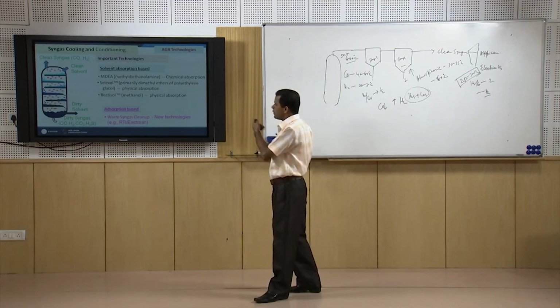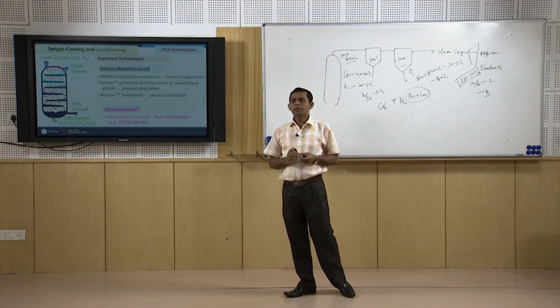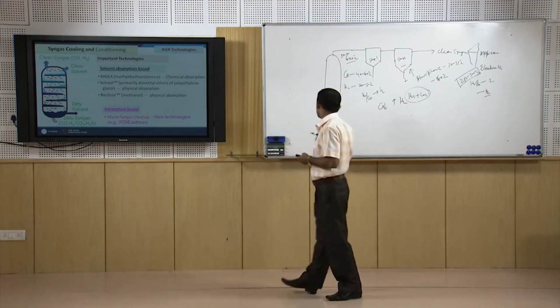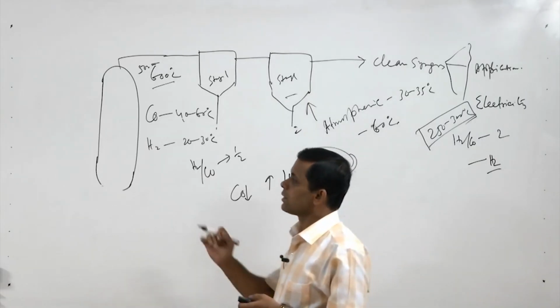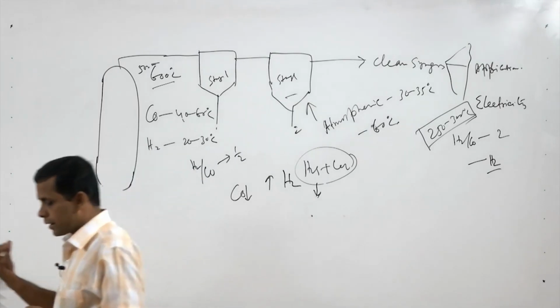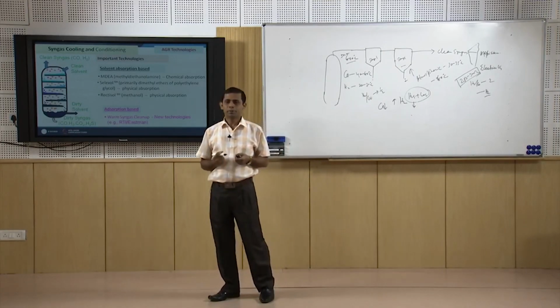So, Rectisol and Selexol capture H2S and CO2 by physical absorption, whereas MDEA captures these impurities from the syngas through chemical absorption.